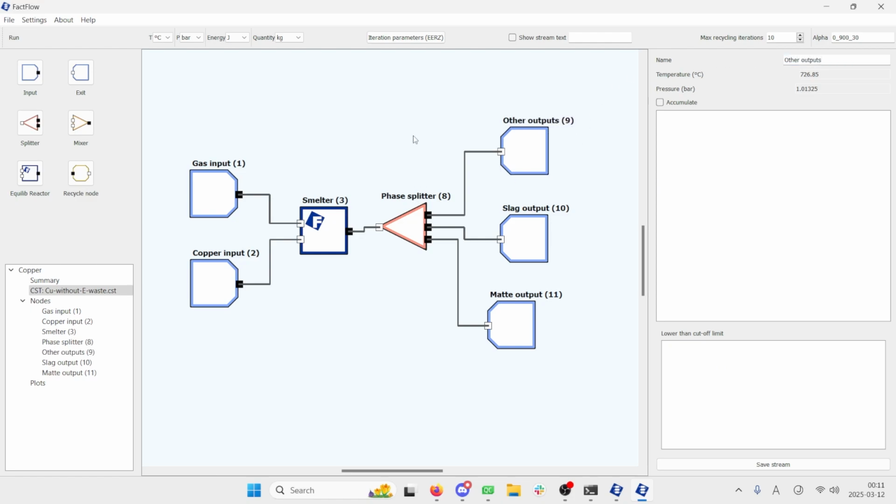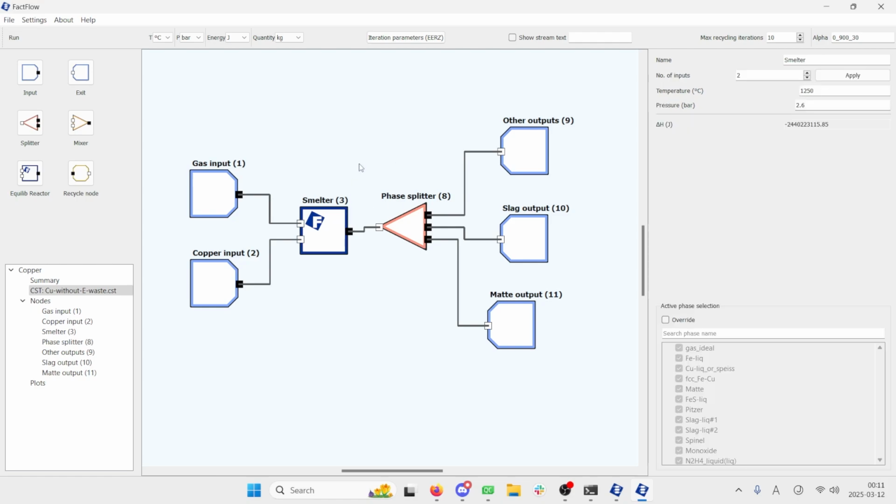Now we've basically set up our flow sheet, and if I click on run here, it's going to start calculating for each amount for the alpha. So you can see on the top right, the alpha is evolving and changing, and the alpha corresponds, like we saw earlier, to the total quantity of the air that we're injecting. And so we can tell, if I react basically the chalcopyrite with this variable quantity of air, how is that going to change the phase assemblage? Is basically what it is.